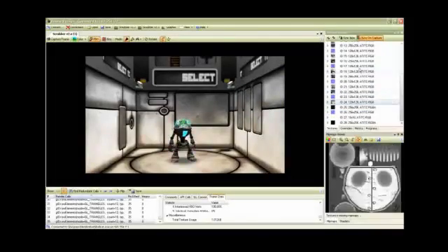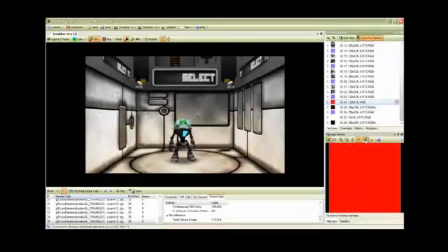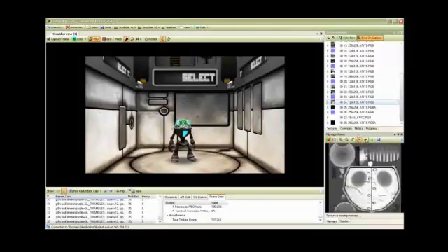And there are a few things you can do here. If it's a texture with an alpha channel, you can view that. You can, for bitmaps, override the bitmaps with solid colors. This would allow you to view how effectively you're using bitmaps in a large scene. In addition to just using the default texture, you can override it with the texture from a file. So if you wanted to preview within this window how a different texture might look, you can do that. And then you can take the texture that's been retrieved from the device and save it off to a file.